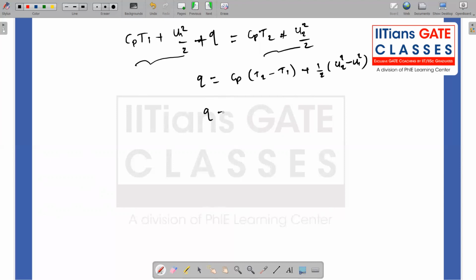So Q is nothing but Cp times T02 minus T01. So this is the change in the total temperature. It's a change in total enthalpy, nothing but the addition of heat is nothing but the change in total enthalpy.